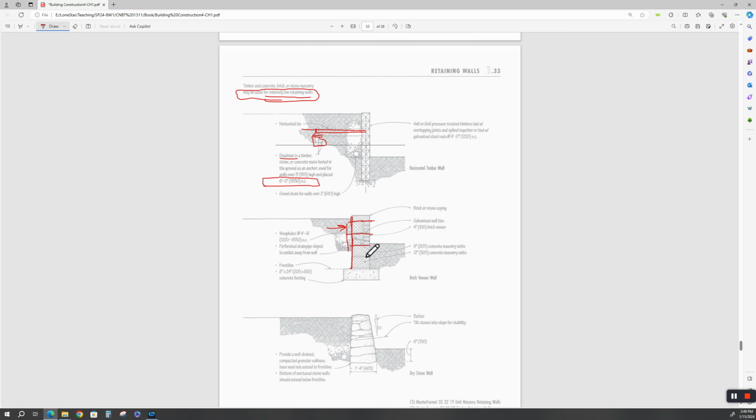They can look cool, but the problem with them is you're going to have to design this masonry as structural masonry, which means these things are going to have reinforcing bars up through the CMUs, the concrete masonry units. You're going to have tiebacks all the way through here, ladder ties back in, and if not, you're going to end up having a maintenance headache.